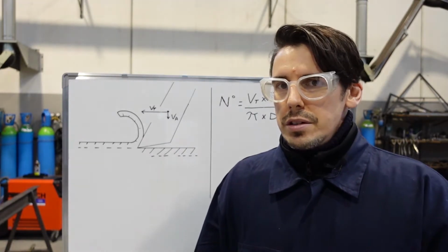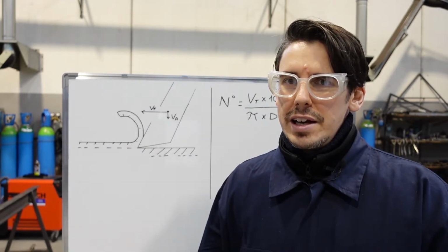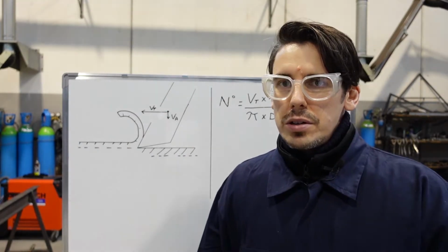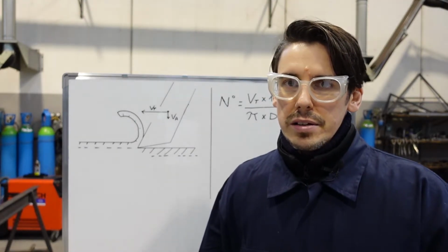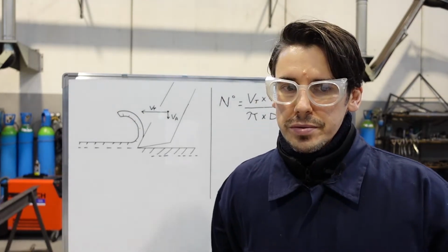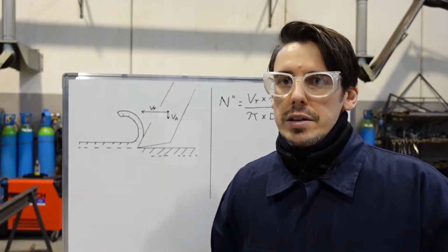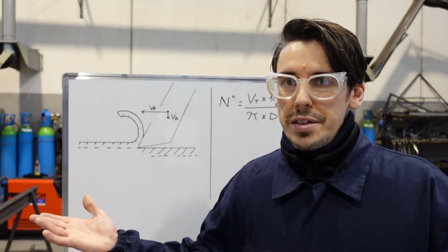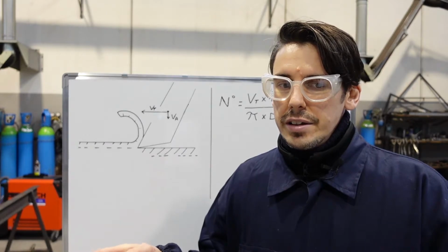Second, the value is influenced by the geometry of the tool, the famous cutting edge while working on the piece, the famous sharpness. Because if we don't have a good geometry, the chip removal is bad and generates more heat compared to the optimal situation. Thirdly, the cooling method. There's a lot of difference between a simple air-cooled system, the air we breathe, and a jet of coolant shot directly in the process area.